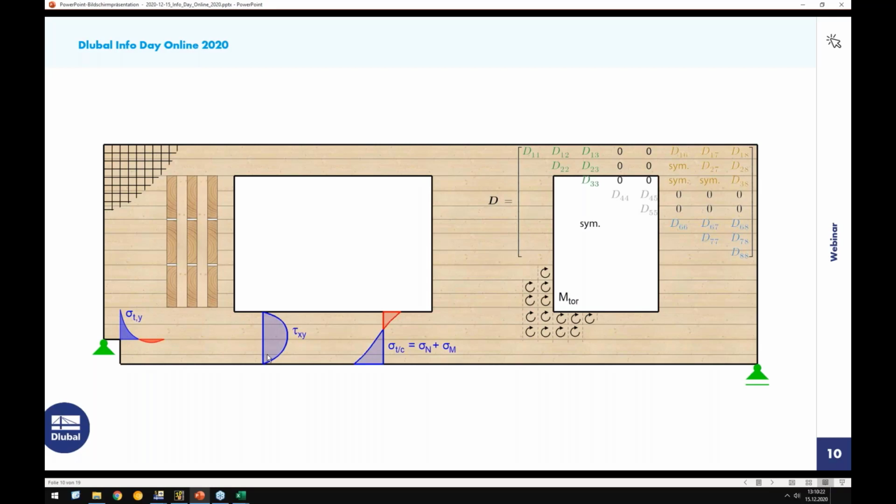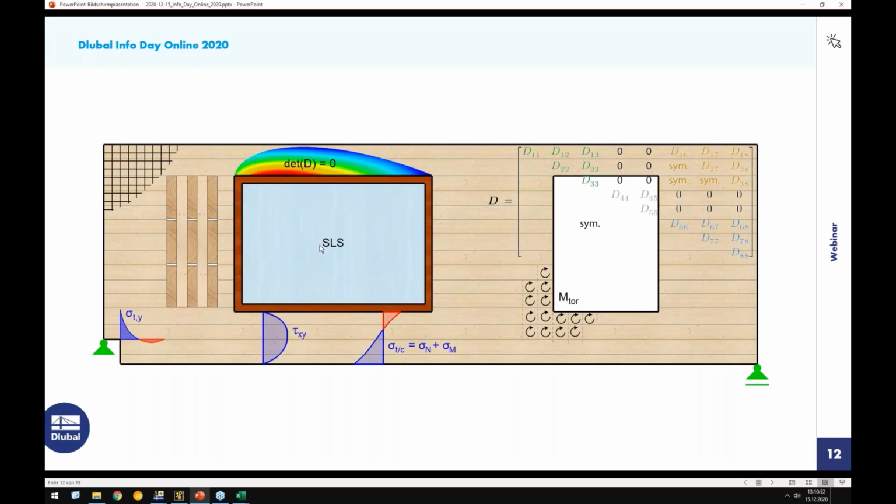Of course, we check our normal shear stresses, we check our normal stresses. Maybe buckling can occur. So in this case, we have roof beams and floor beams. But you can imagine when this acts as a one-span beam, the upper chord is under compression. So therefore, it can happen that the bottom side of this upper chord can buckle out somehow. This is a fact we will check. And of course, the window must work also in the deformed shape, so it should not get any crack or get destroyed. So we need to check the deformations, especially the deformation inside here, and of course the global deformation.